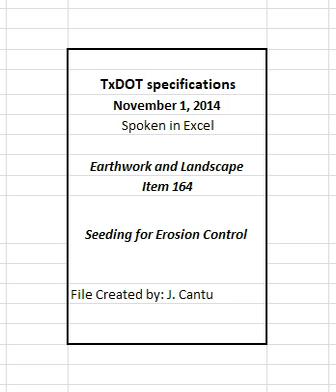Apply fertilizer in conformance with Article 166.3, Construction. Seed and fertilizer may be distributed simultaneously during broadcast seeding operations, provided each component is applied at the specified rate. Apply half of the required fertilizer during the temporary seeding operation and the other half during the permanent seeding operation when temporary and permanent seeding are both specified for the same area. Water the seeded areas at the rates and frequencies as shown on the plans or as directed.